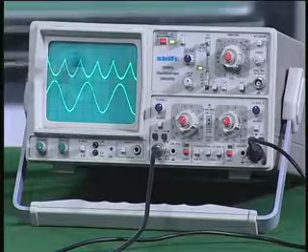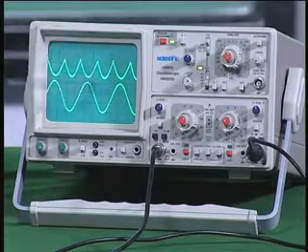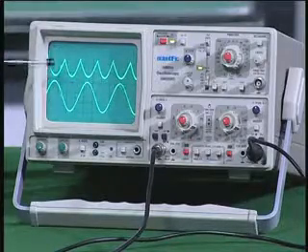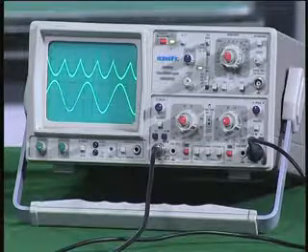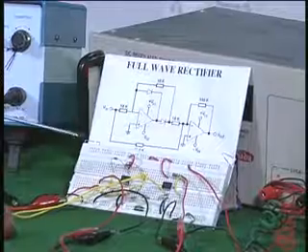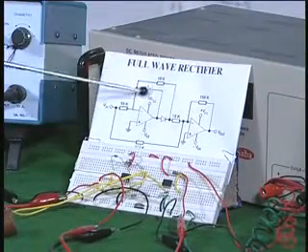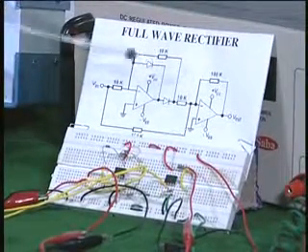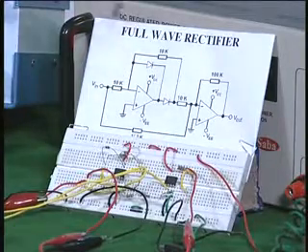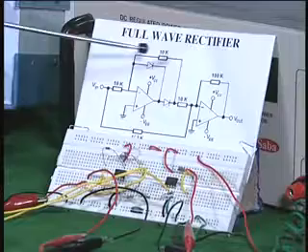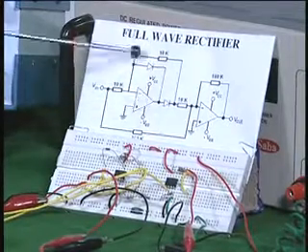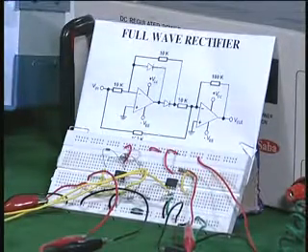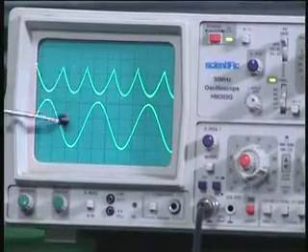You can see both the halves are coming in the bottom, and if you want the signal coming up to the positive side, all you have to do is interchange the diodes that you have seen in the circuit. For example, if you invert these two diodes, changing the orientation, then you will get the full wave rectified signal for the other side. So you can do full wave rectification easily by using one half wave rectifier and another summing amplifier. By properly choosing the gain, you will be in a position to get a full wave rectified output as you have seen on the oscilloscope.